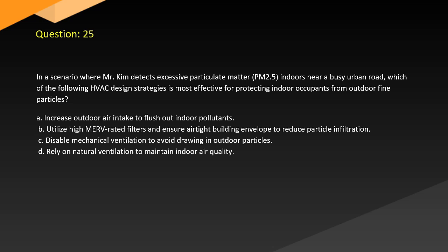Question 25. In a scenario where Mr. Kim detects excessive particulate matter, PM2.5, indoors near a busy urban road, which of the following HVAC design strategies is most effective for protecting indoor occupants from outdoor fine particles? A. Increase outdoor air intake to flush out indoor pollutants. B. Utilize high MERV rated filters and ensure an airtight building envelope to reduce particle infiltration. C. Disable mechanical ventilation to avoid drawing in outdoor particles. D. Rely on natural ventilation to maintain indoor air quality.